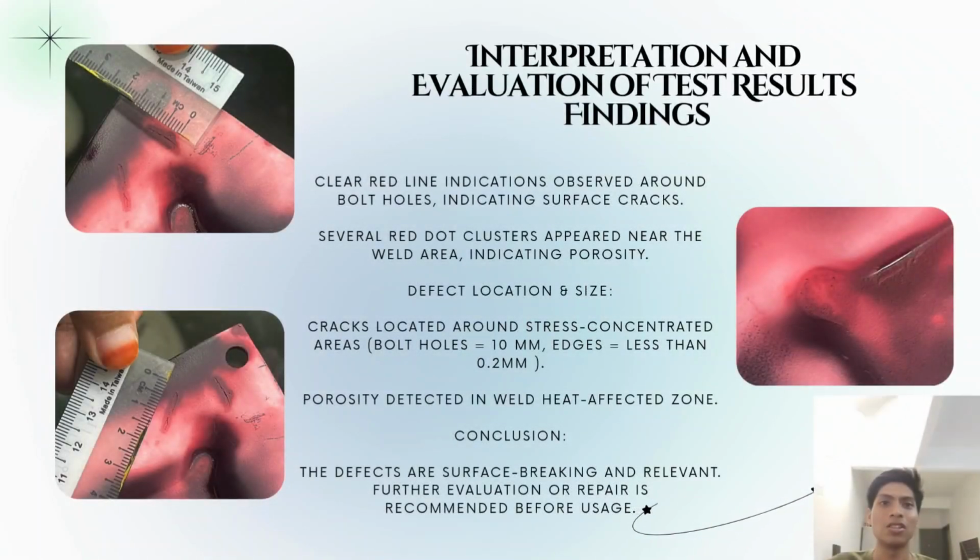Assalamualaikum, my name is Muhammad Azri Naimi bin Rizwan. This slide shows the evaluation of our test result using dye penetrant inspection. We can clearly observe red line indications around the bolt holes. This line indicates the presence of a surface crack, likely caused by stress concentration.